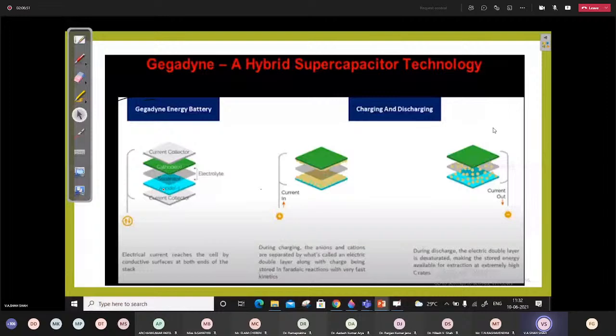The power requirement of the vehicle can be calculated based on the essential data required for the computation of the vehicle power: the required speed, efficiency of the motor, rolling resistance, coefficient of drag, area of the vehicle, radius of the wheel, and mass factor.